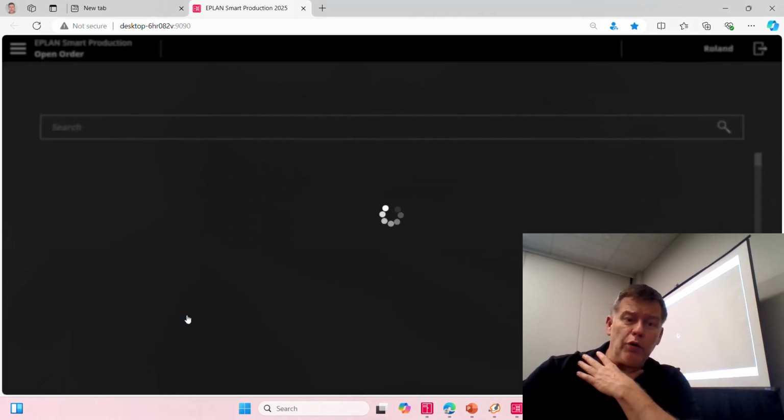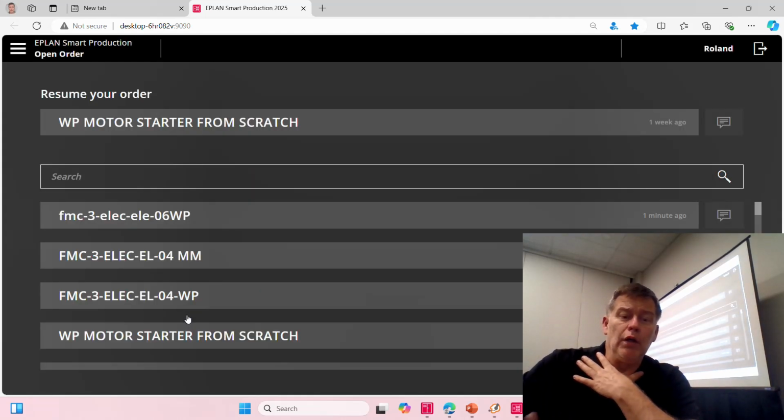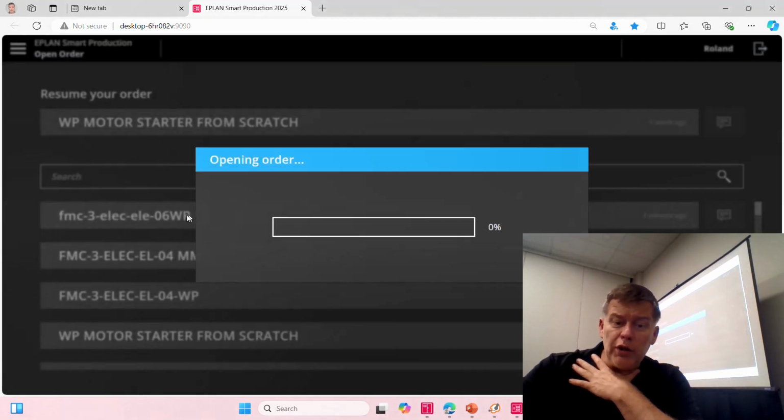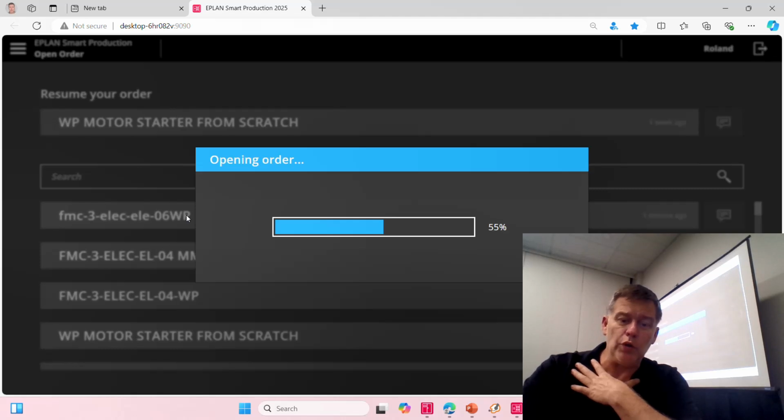Of course, as we saw earlier in that PowerPoint, before we can even start putting in the wires, we shall do the installation. Now, again, like I said, if you have smart mounting licenses aside of your smart wiring licenses, you will also have access to these 2 additional tabs, which are the ducts and rails and the components. You will see in 2 seconds the devices. So this will help you in the assembly of the panel before you can do the wiring.